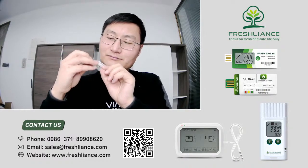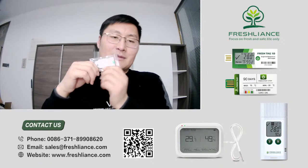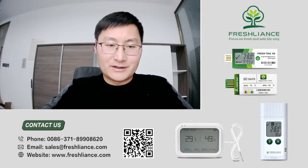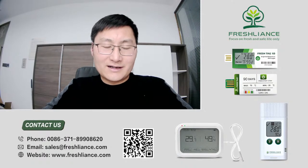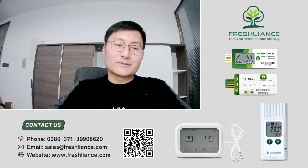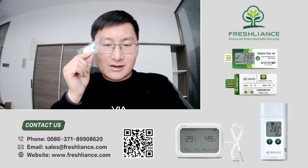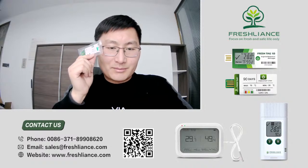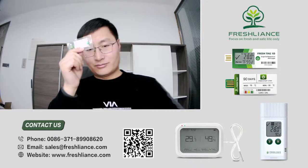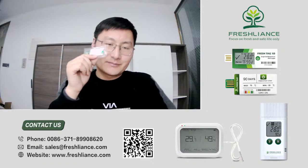Here, LED indications, 3 different colors. Resolution 0.1 degrees. Start delay can be set from 0 minute to 24 hours. Log interval is from 1 minute to 24 hours. Report format could be PDF, could be CSV, could be PDF and CSV.